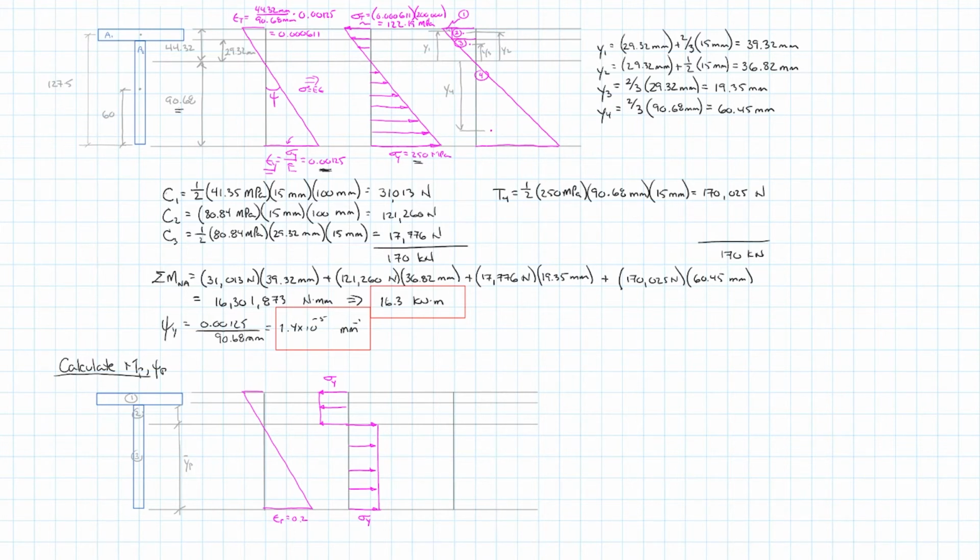I'm going to draw it out again without the arrows and everything, just so we can break it up into those simple shapes that allow us to calculate the moment capacity. I'll put in the actual values for our strains and our simple areas in this case. So we're going to again have to break it where the flange and the web meet because the thicknesses are different.